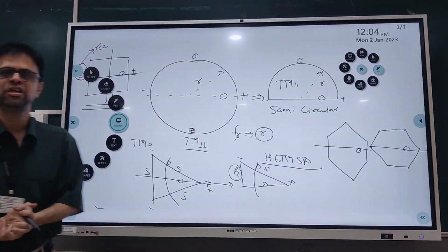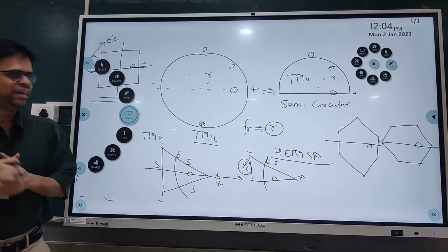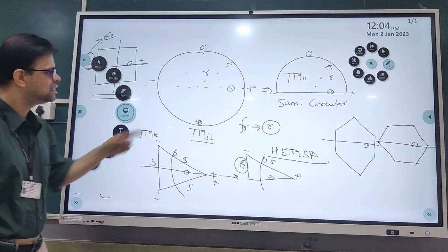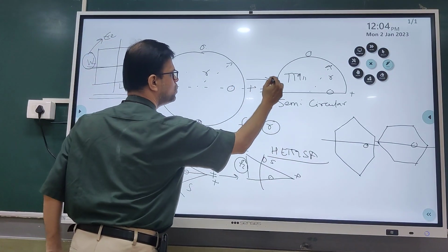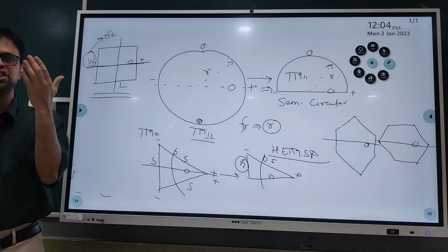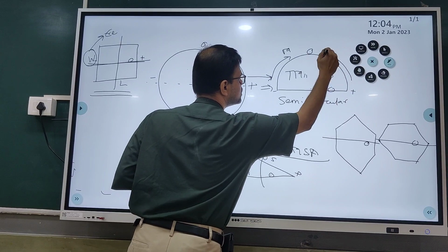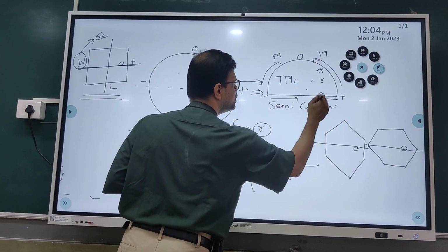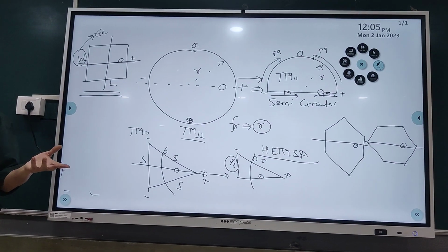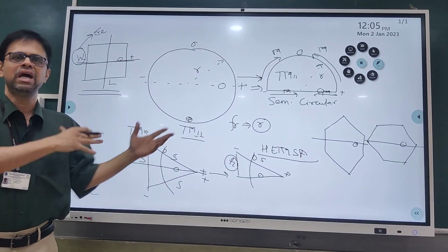Remember, for that cross polar radiation, you always need to consider the distribution of fields around the patch geometry. Here, the distribution of field is symmetrical with respect to the circular patch, whereas going from here to here, the distribution has been disturbed. That actually changes the equivalent magnetic dipole model around the patch geometry. This is the equivalent magnetic dipole model, which is drawn with respect to the fringing fields.